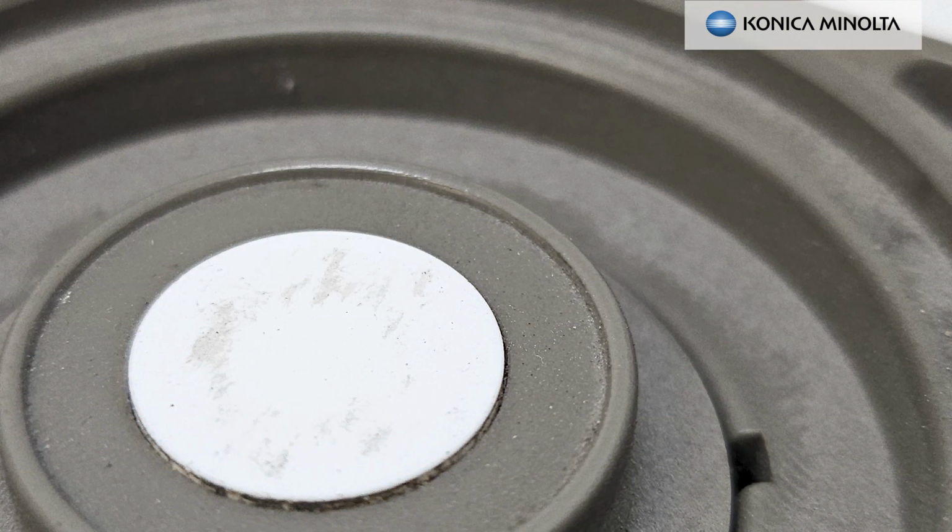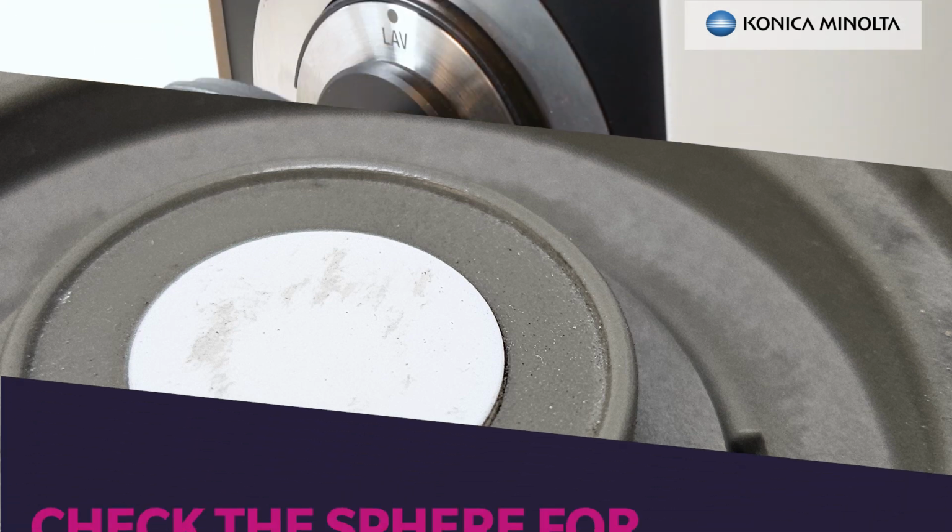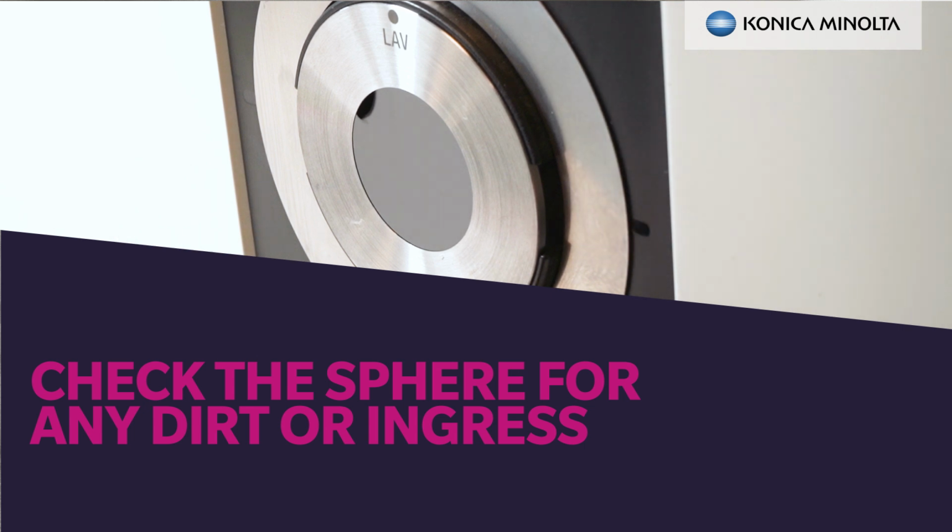When performing white calibration, you should check that the tile is the correct tile for that instrument, that it's in good condition and free from fingerprints, dirt and scratches. You should also regularly check your instrument, particularly the sphere, for any dirt or ingress. Never put anything inside the sphere to try and clean it. If any dirt enters the sphere, then the instrument should be sent to the manufacturer for service. The barium sulfate coating of the sphere is extremely fragile, and any damage can greatly affect measured data.